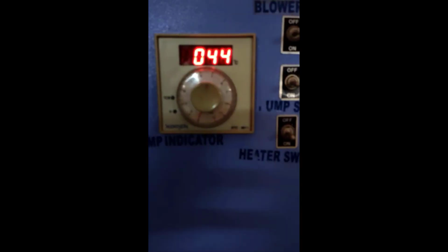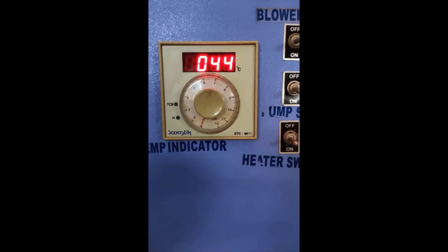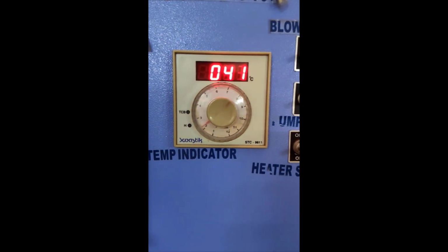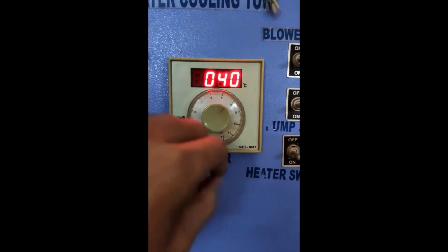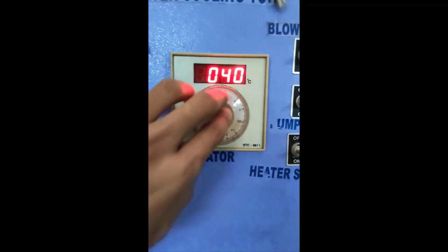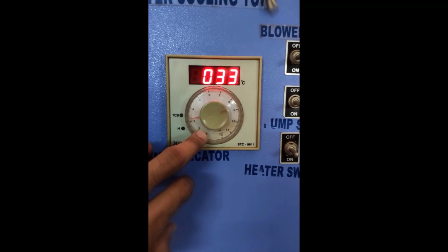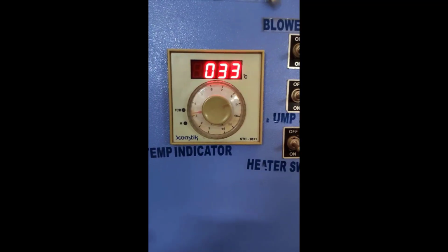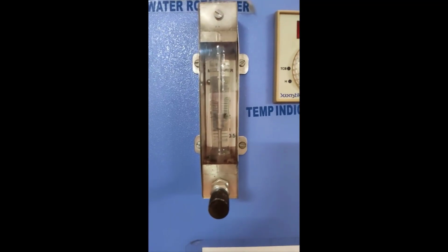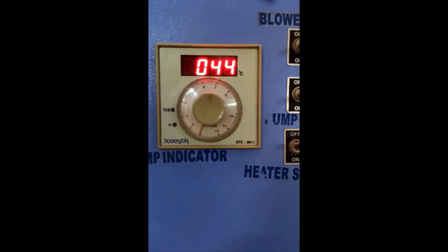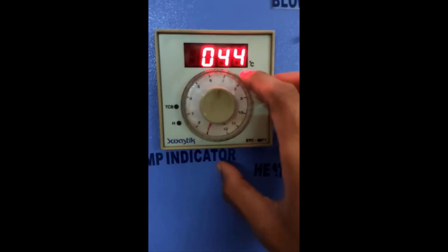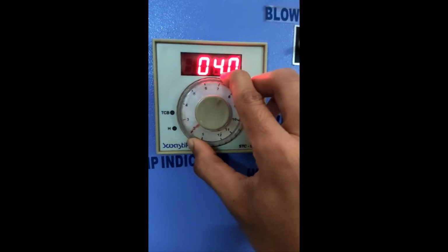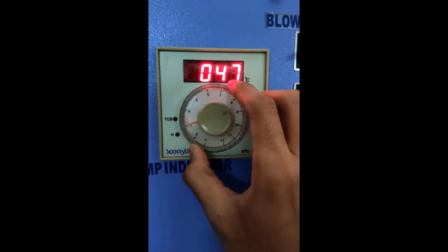Now we will note down three different temperatures. This channel 1 is the hot water inlet temperature, channel 2 will indicate the dry bulb temperature of the inlet air, and channel 3 will indicate the wet bulb temperature of the inlet air. Like this we will note down these temperatures. Now after some 10 minutes, or steady state, we will again note down the temperatures, but this time for the outlets, like the cold water outlet and also the air outlets.